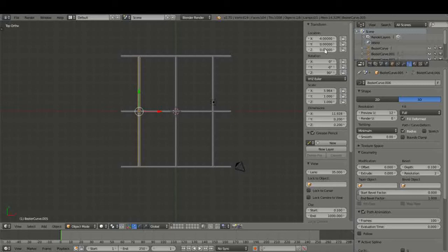Okay, it's very good practice to use the location settings to enter the positions so that you've got it exactly in place, especially when you're working with the physics engine. Sometimes you'll find that the object is 4.0001, and that can make a huge difference with your simulations and so on. But anyway, besides that, let's just stick with this, and I'm going to now do the curly bits.